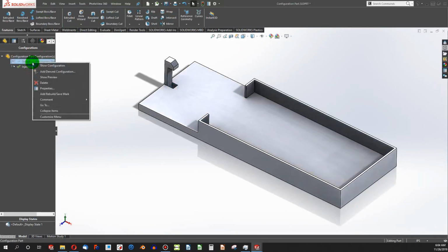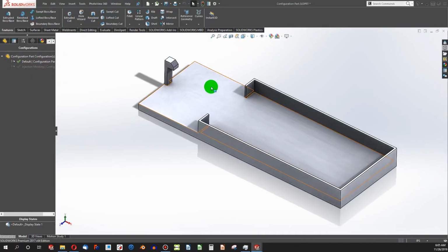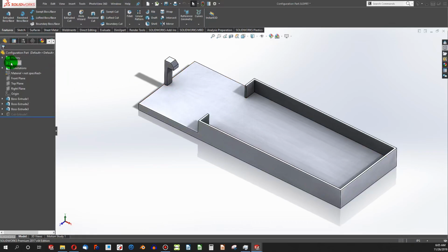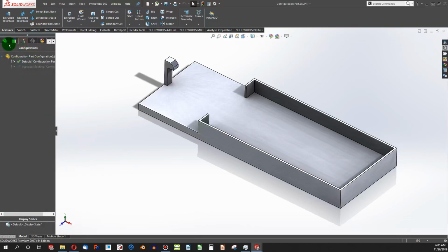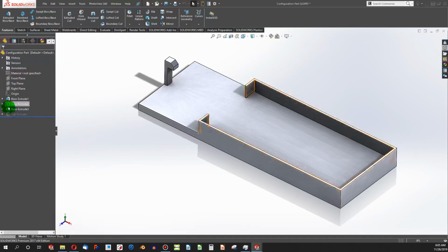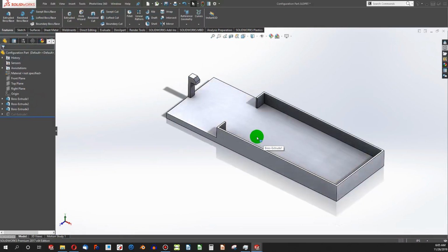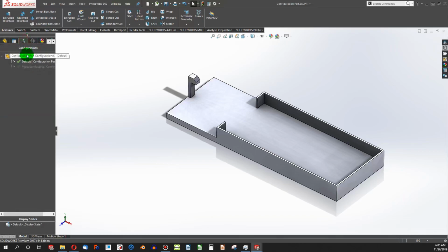And if I go back to my normal configuration, that is no longer there. I can go to my feature design tree in my default 3D printed configuration, and the cut extrude is suppressed. I can activate this cut extrude in the configuration simply by unsuppressing, but I would like to leave it out. So lesson number 1 for configurations is when I add a new feature, it will be unique among the two configurations.